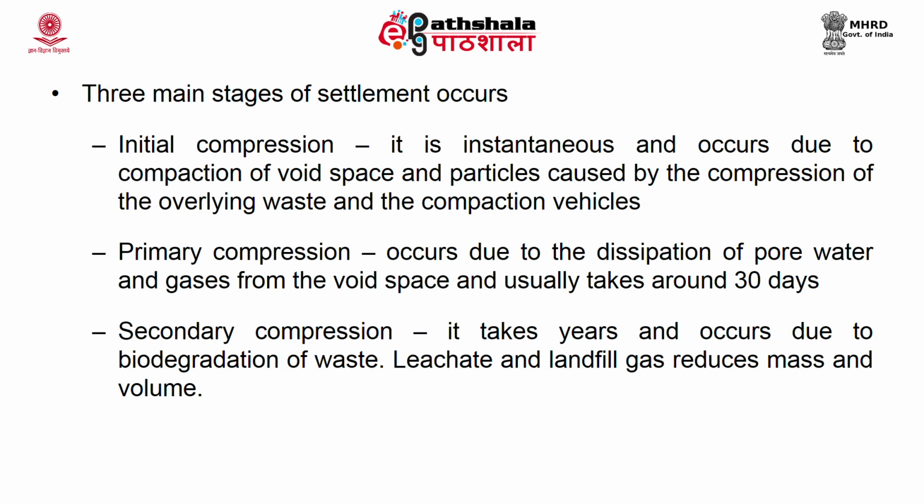So, the more the compaction, the void spaces will go, the air space in between these particles will go off and it gets compacted. It occurs due to compression pressure from the overlaying waste and the compaction vehicles. The second type of settlement is called the primary compression, which occurs due to the dissipation of the leachate or the water and gases from the void spaces, and it usually takes 30 days.